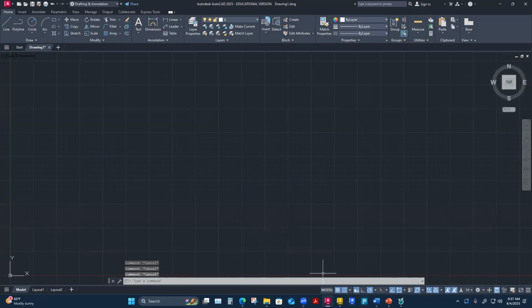But if I turn off dynamic input and I go into that same command, see, I'm in the command, but I don't get the command line prompt. I kind of like it, so I usually leave on my dynamic input and then it looks like that. It gives me the coordinates, gives me other things, and my eye looks at that easier. Some people get annoyed by that hanging around with them. It tends to become background to me, but it's helpful when I'm in a command that has multiple options.